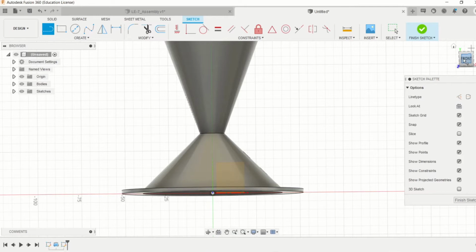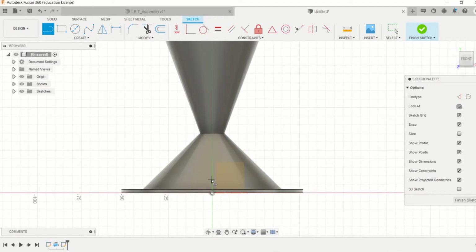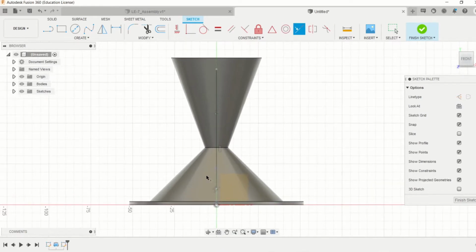In this case I'm just going to draw a line with a certain length. Now pick the collinear, make sure it coincides with the y-axis. Now let's give it a certain length. Let's say in this case just 75, and this at a distance from the top.